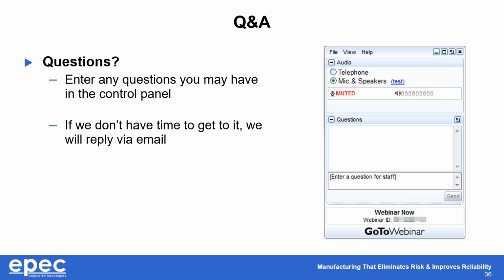However, there are manufacturing defects that occur. Could be a training issue, could be an equipment issue, but the HiPot is a great way to root out some of those. And in doing so, what you're effectively doing is you're making sure there's no live components or no way that a person or other equipment is going to get shocked or electrocuted.